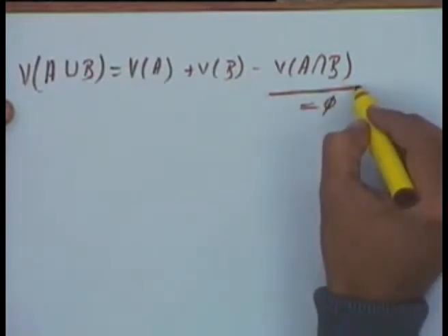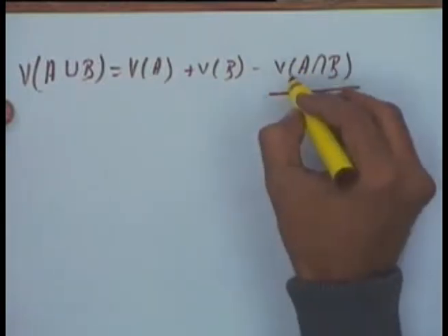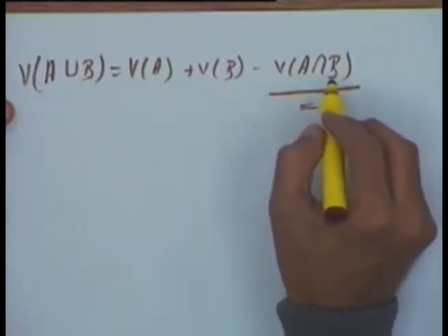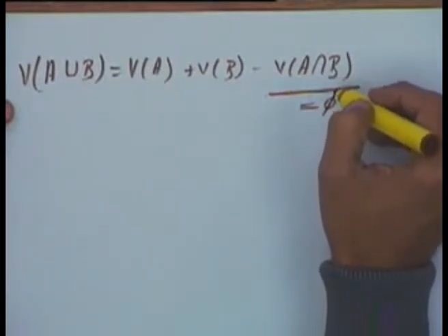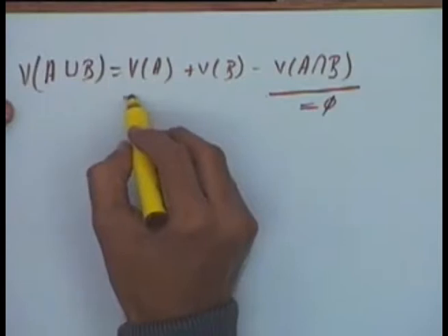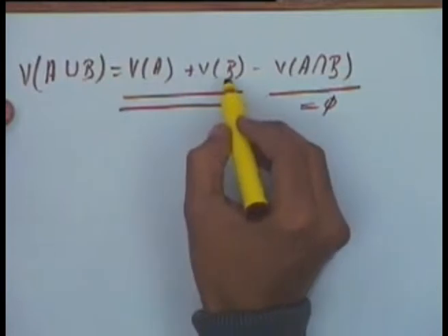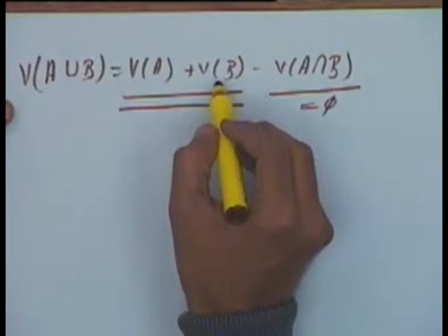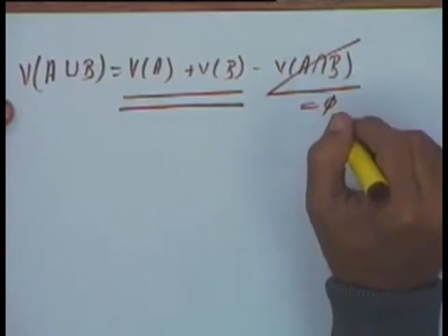then the volume of A intersection B will always be 0. So there are modeling techniques which ensure that A intersection B will always be 0. The intersection of all solids will always be 0 in that case. We will see some of those modeling techniques. So in that case we can easily use this method of finding out the volumes, because A and B will be primitives or will be derived from primitives. So the volume of the objects can be easily computed. And we know that the intersection will always be 0, so we will always ignore this term.